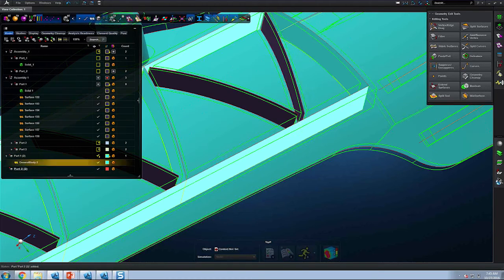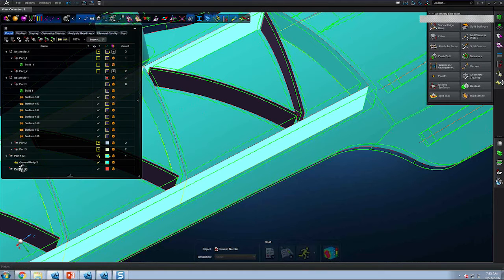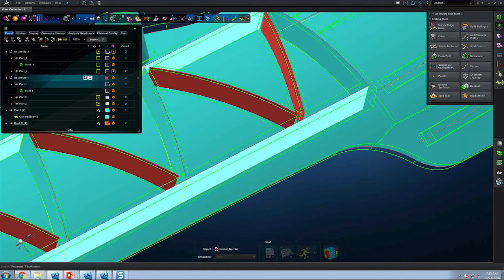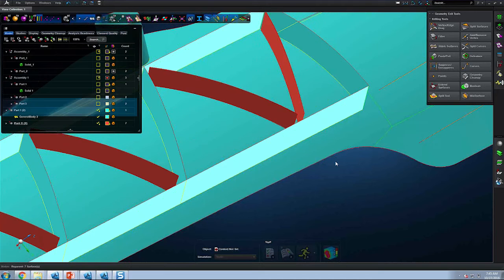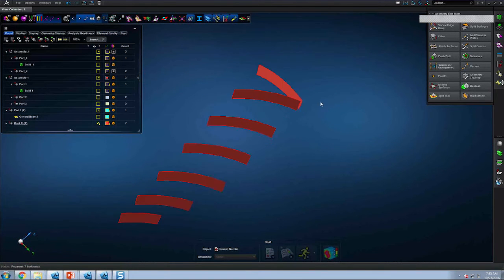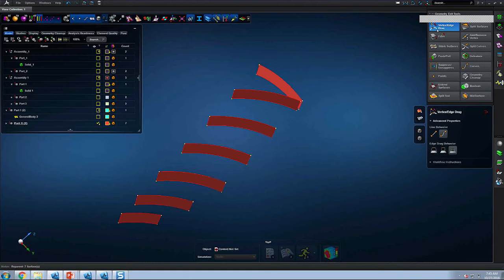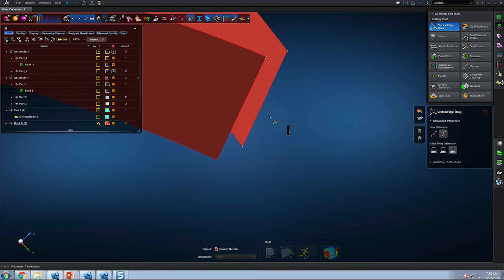And just for better effect, I think I'll isolate these faces too. And so here are the pieces where I want to extrude the free edges so I can join these to the rest of the mid-surface geometry. But here, if I were to extend this piece, you find that there's an issue.